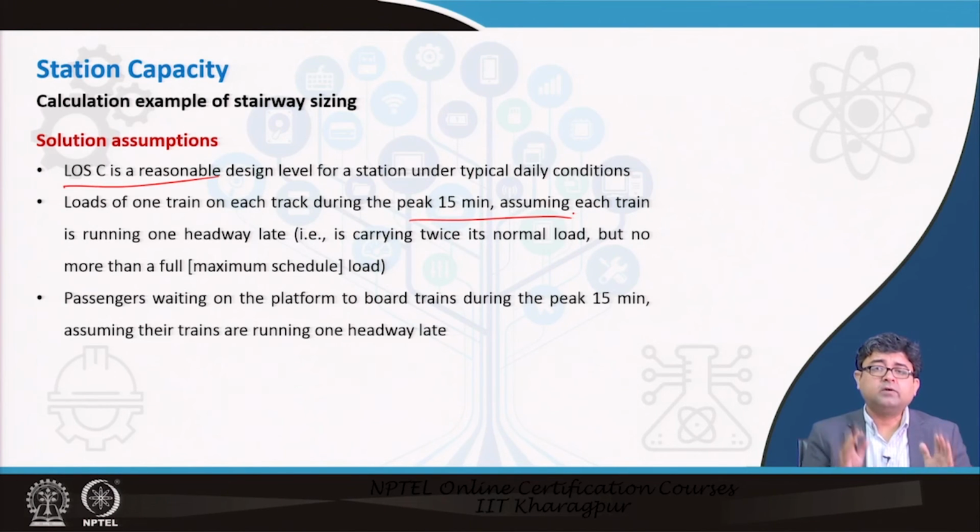So, you always design for the peak hour, right. We have looked at this in other calculations also, calculations of level of service of pedestrians and bicycles. Always calculate it for the peak hours, because in the peak hour your system has to hold up to the volume or the flow of people coming there. If it holds up to that maximum volume or flow, then it will easily hold up to lower volumes and lower flows during the non-peak hours.